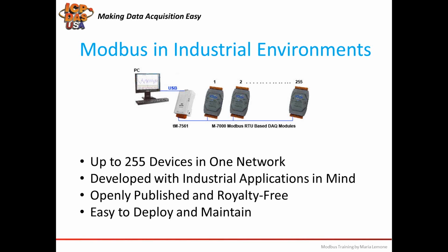Okay, and then Don asked, what is the range of the Zigbee wireless devices, and is it shorter communicating through several walls? A lot of our Zigbee equipment has a default communication distance of about 700 meters, and you can use antennas to extend the operating communication distance up to several kilometers. And each end device in the Zigbee network acts as a slave, so it repeats the signal.